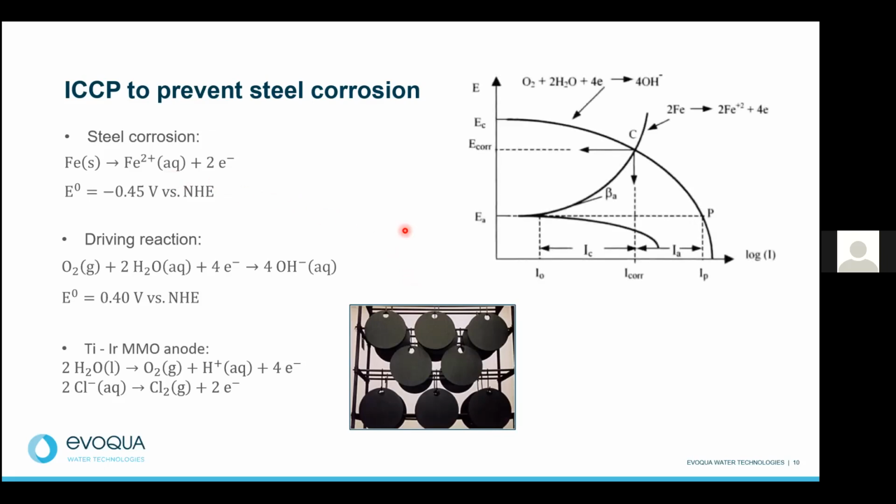So to illustrate this a bit further, I want to discuss this figure. Corrosion, which is of course what happens to iron here, is a kinetic phenomenon, and it involves mixed potentials. So what this means is that when the structure is left without any external driving force in the atmosphere, you will have two reactions that dominate on the surface, which are, as mentioned, oxygen reduction, which is this curve shown here, and iron oxidation, the iron dissolution curve shown over here.